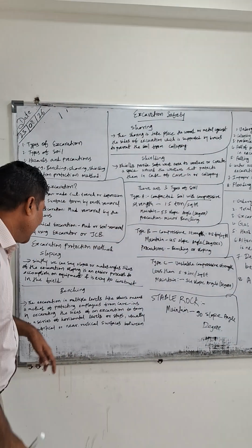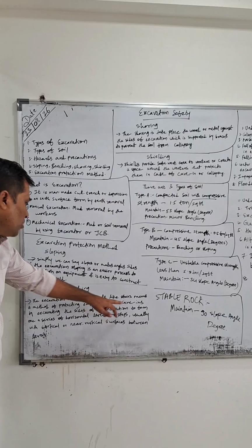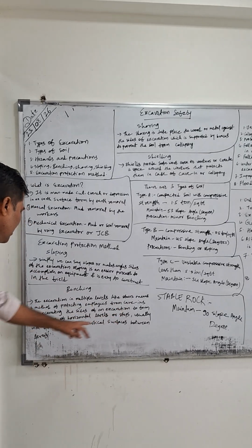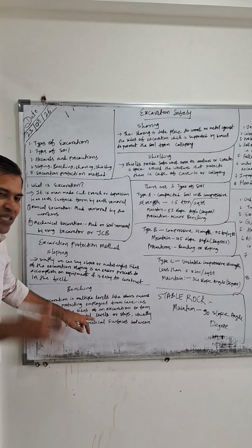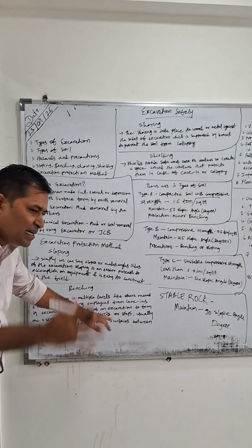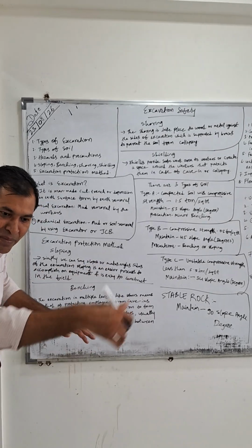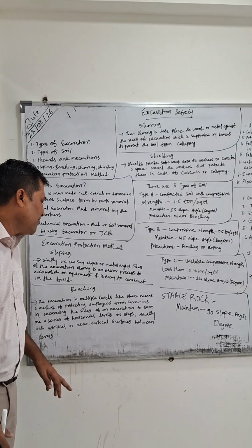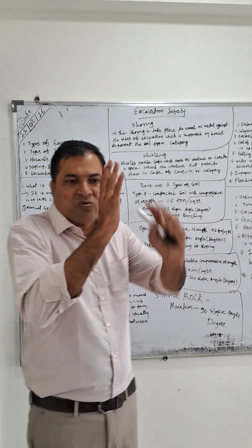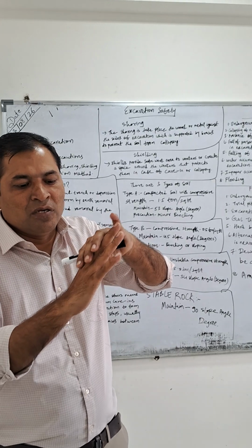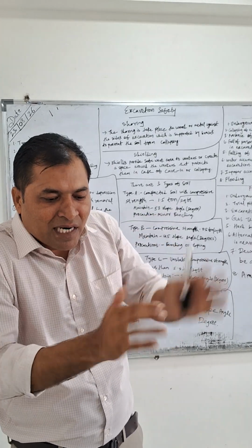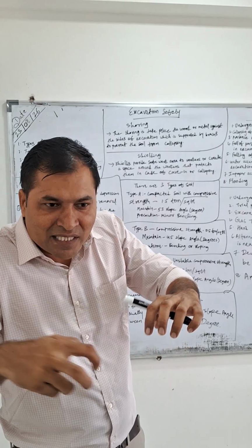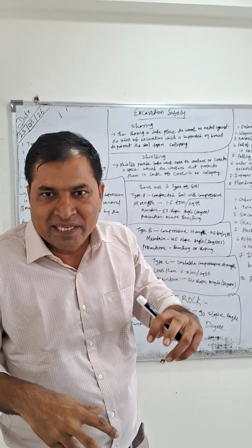So yes, it is very important. That is the protecting of employees from cave-ins, by excavating the sides of an excavation in a series of horizontal levels. Always go with the levels. Cut the mud in a level, then make the bench and then go down. Ideally the surface is vertical or near vertical. Vertical means what? It's like a standing position. So it is better to cut that part, make a bench, again cut that part, again make a bench. Step by step the workers go down with the help of benching.